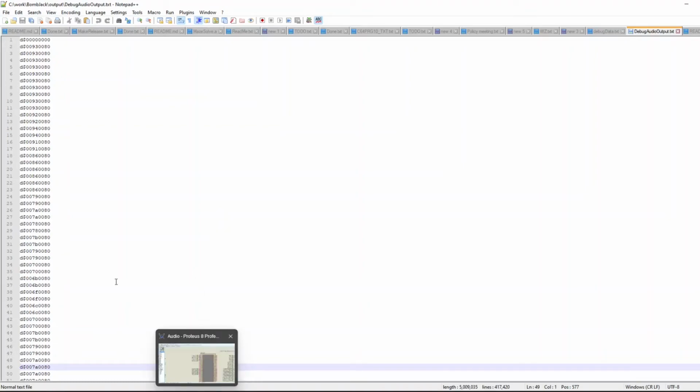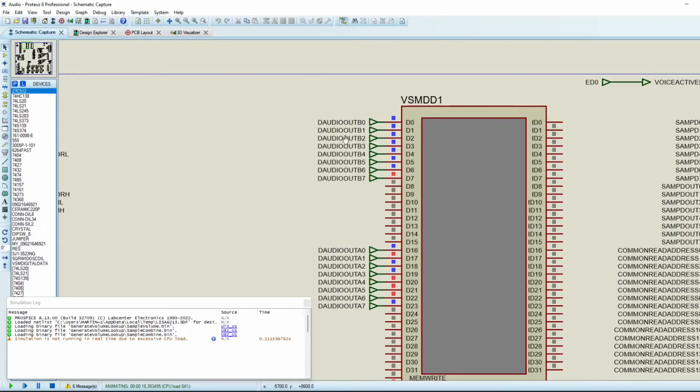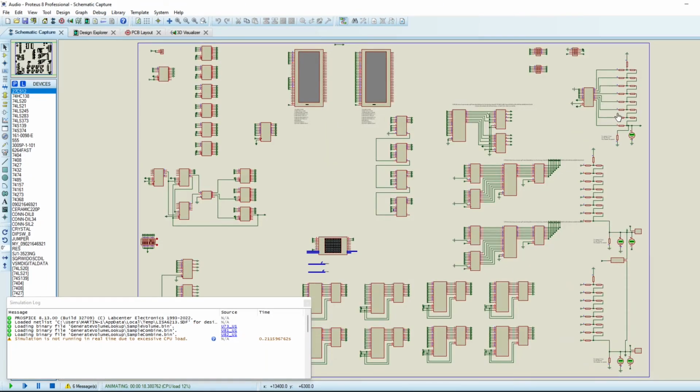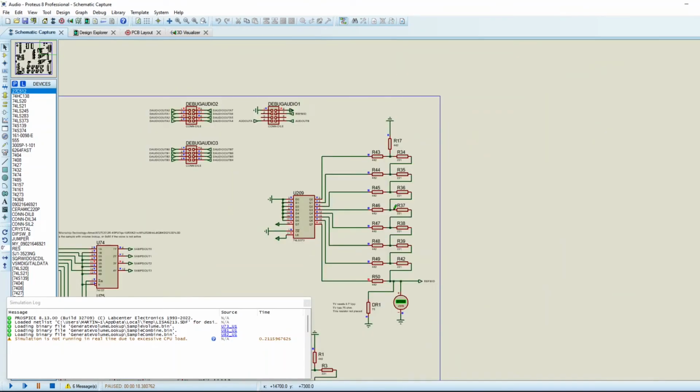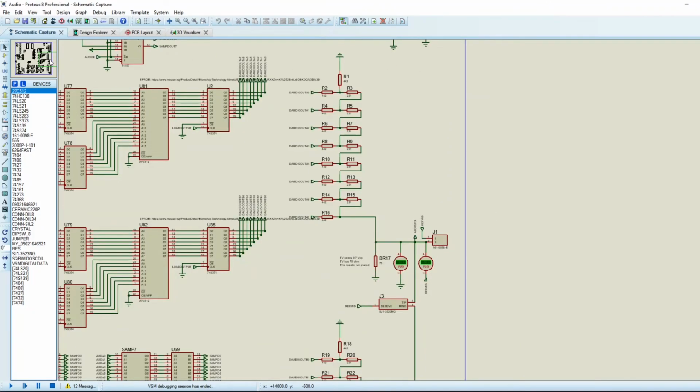The only thing that this digital data output model of validation doesn't finally check is, of course, the final output of the resistor ladders. And that's because when running the simulator with all of these resistor ladders, which are analog components, enabled, the simulation is noticeably a lot slower. Now, this means that these voltmeters here, when the simulation is running without all of this activated, of course, the voltages won't be correct.